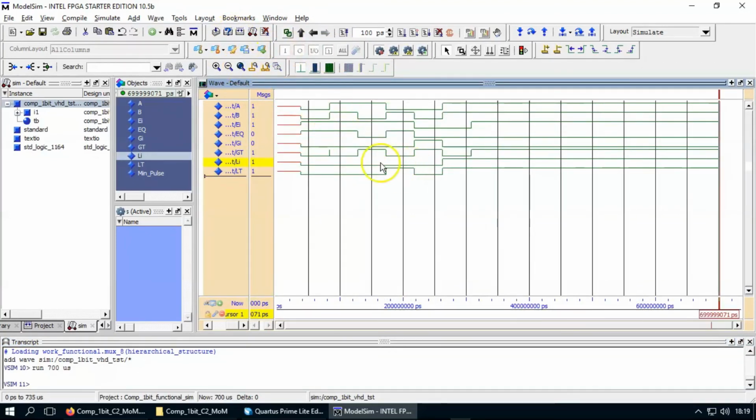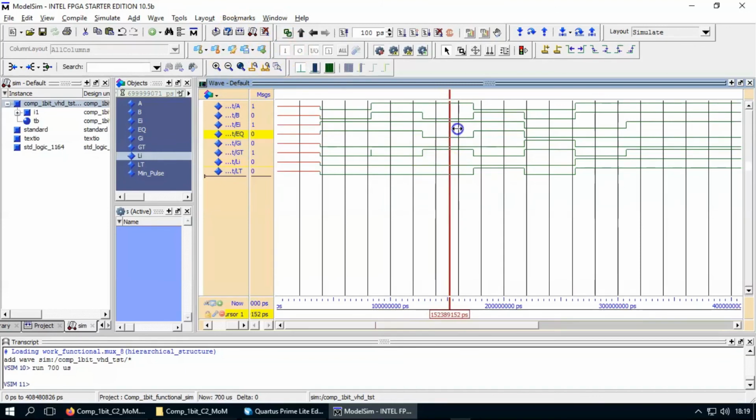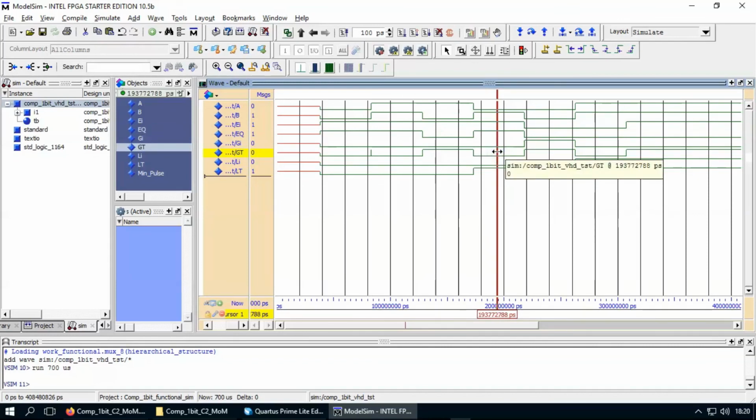Let's zoom the full window, the full list of stimulus, and now let's see. 1, 0, very well, and now 0, 1, 1, whatever, 0, 1. Yes, it has now been corrected. So you see the error has been detected and corrected. Theoretically, if you are a test engineer, you have to do that for the 32 possible situations, and naturally you then have to do that automatically using assert instructions in VHDL and things like that.